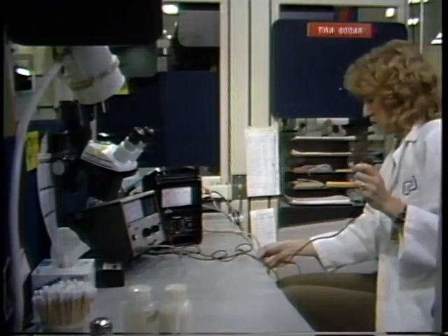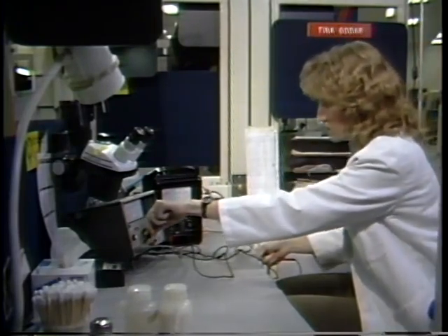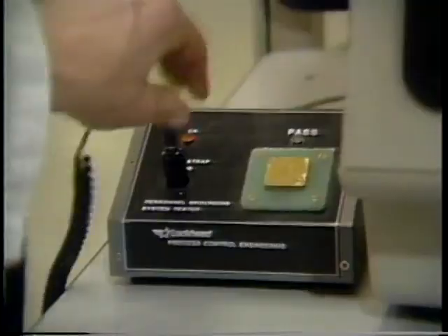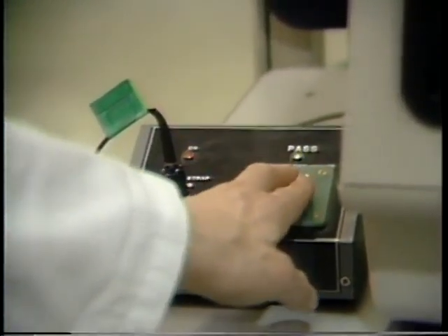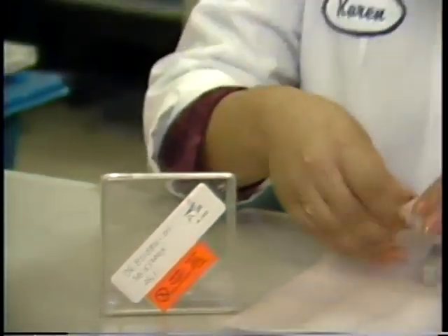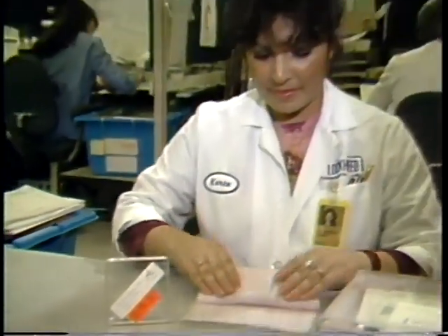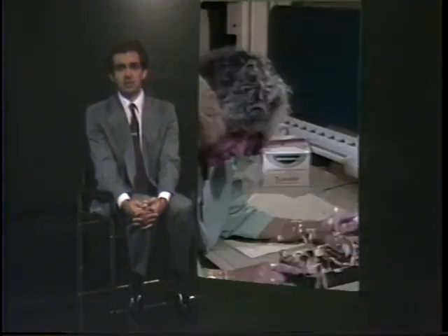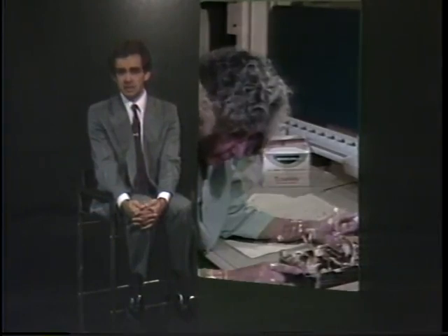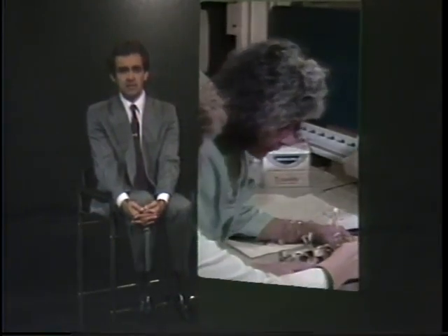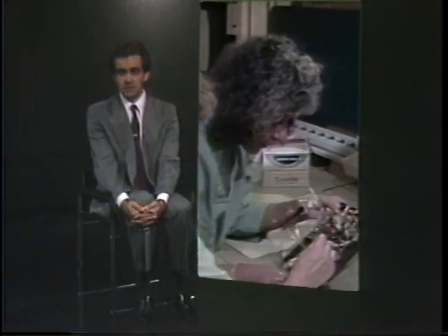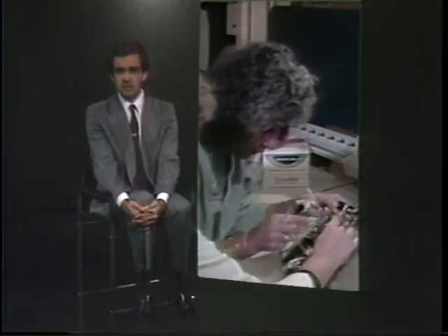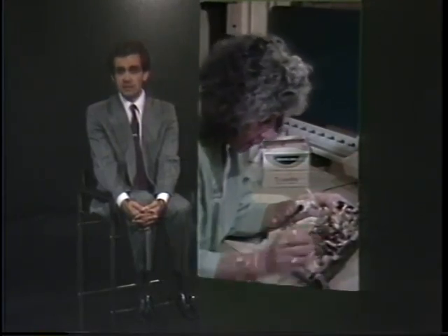Process control engineering verifies that the equipment and workstations are ESD safe, but the area won't remain that way without your help. ESD controls are built into each step in the process to protect sensitive hardware. Unprotected items can become damaged or even destroyed. A common type of damage is a slight degradation which may not even be detected in test. This type of damage is a latent or hidden defect and may result in a failure. These defects are very serious because they can shorten the life of the part.